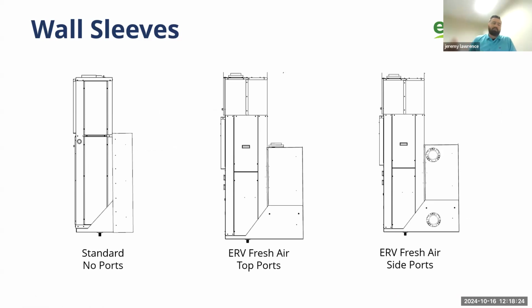So there's no effect of water and rain or snow getting past the condenser where it would get into this drain section here, but if this drain was to ever be plugged, the sleeve is designed to overflow water outside the building before it would flow inside the building.